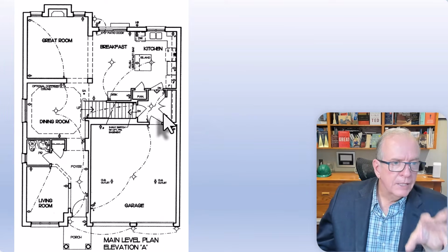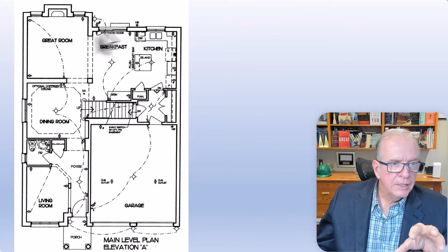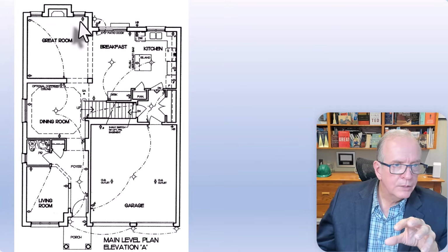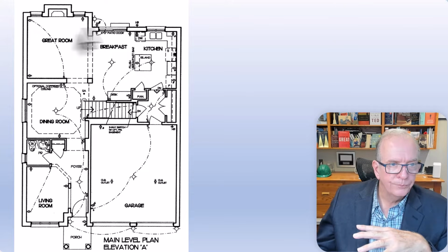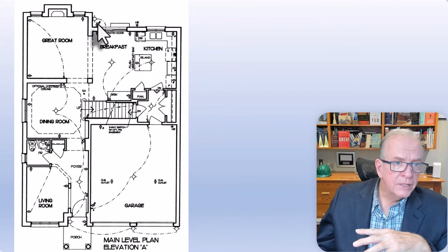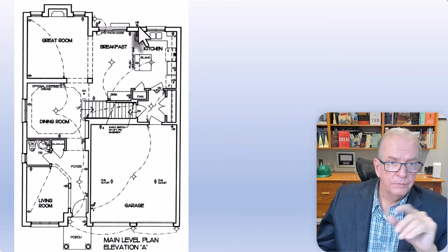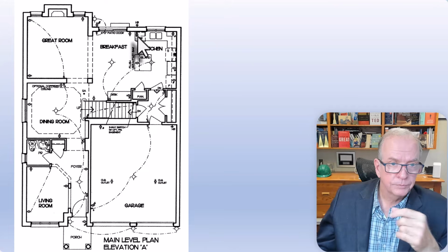So here's basically an electrical plan. And in this electrical plan, we can see a number of things. We can see basically this is a great room. There's the outlets, right? Those are duplex receptacles. So each one's like what I was just showing you. This basically WP means it's a weatherproof outlet. So it's outside, right? So it's going to have a cover. This is a hose bib. So that's where you're going to be able to put your hose.